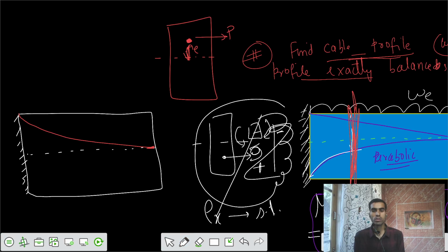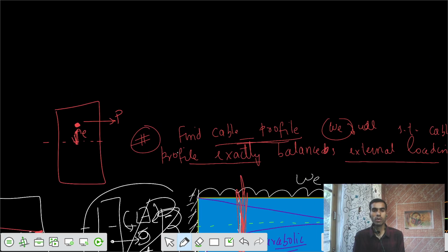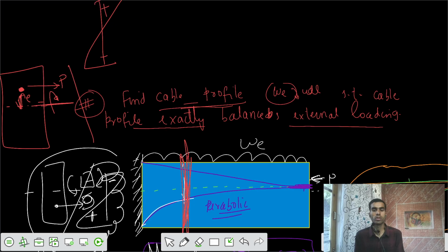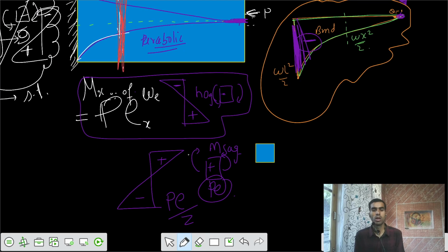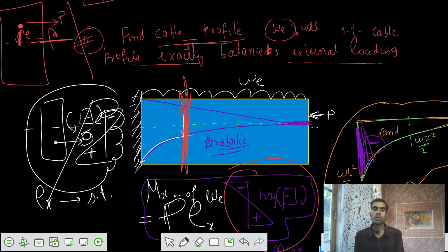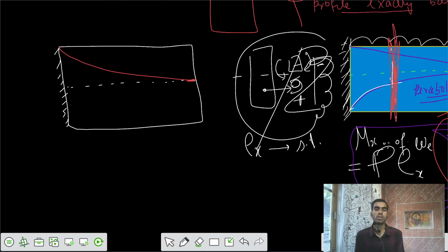It is going to cause a sagging moment about the neutral axis, clockwise. You have this section, and it's having some sagging moment about the neutral axis. So your bending stresses are in this way, positive, negative. That's going to counteract the effects of those external moments, negative, positive. So your final diagram is in this way.